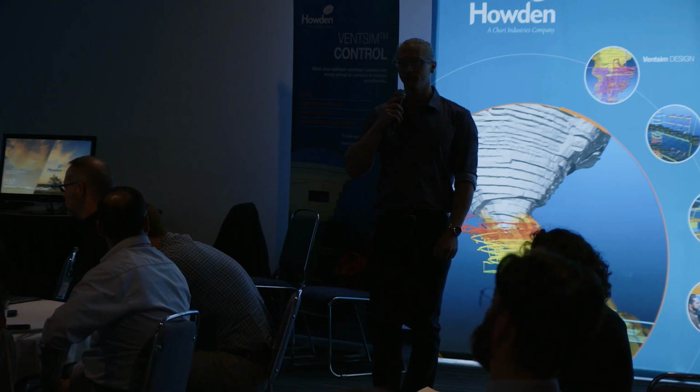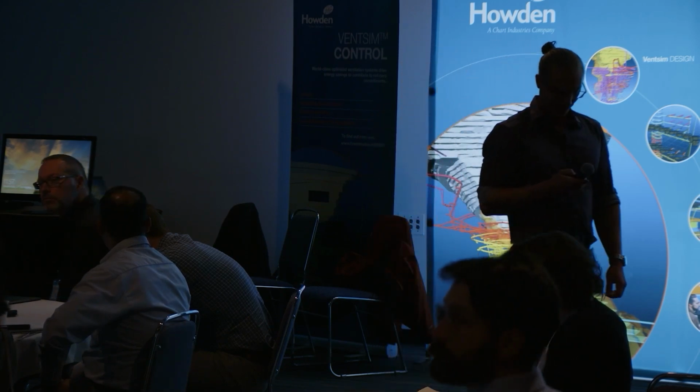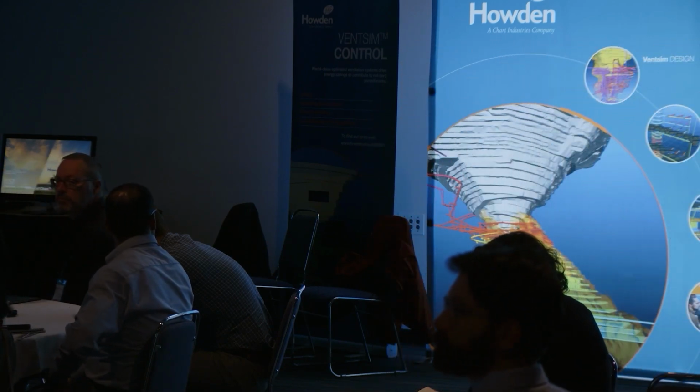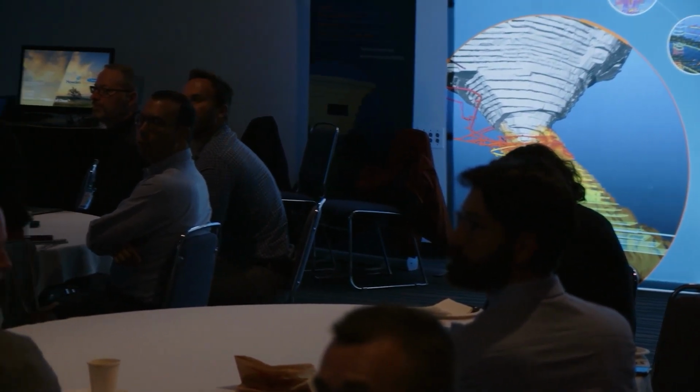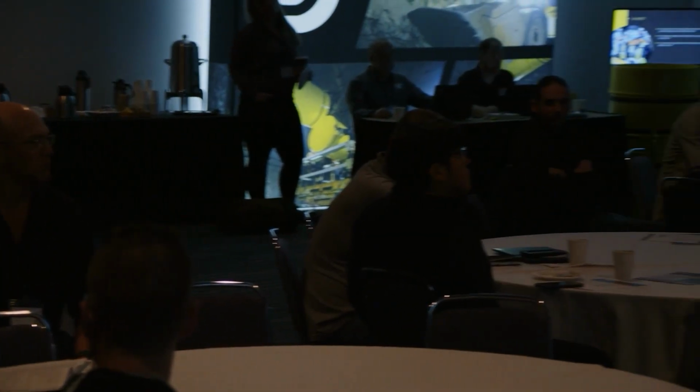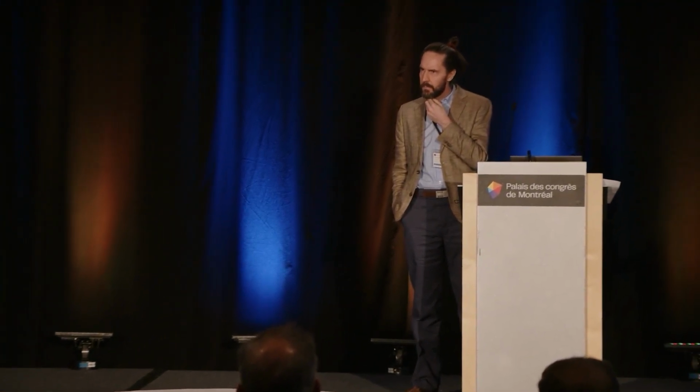Darryl, you had a question? Yeah, thanks for the talk, Dr. Griffith. We talked about indirect and direct fired heaters. With indirect fired heaters, we have the benefit that we can capture the latent heat of vaporization in the combustion products, so we get more heat out of the fuel. Is there a setting where we can input either a lower heating value or higher heating value for natural gas, let's say?